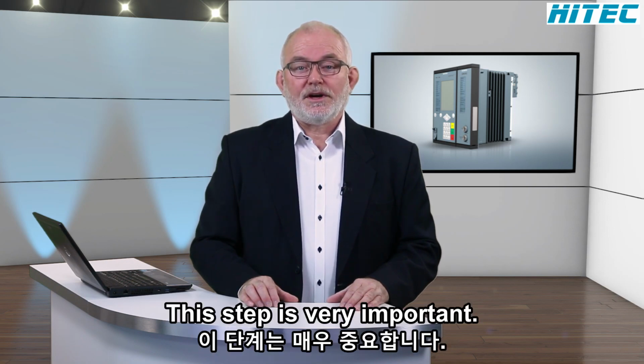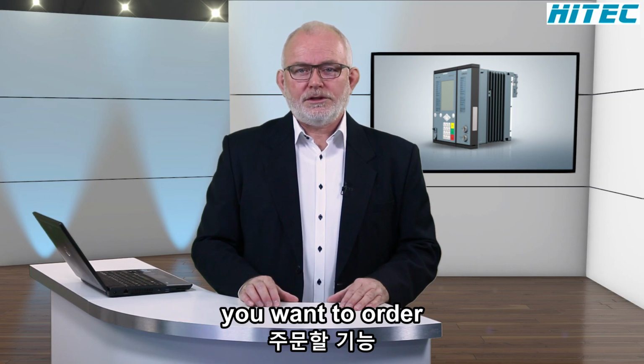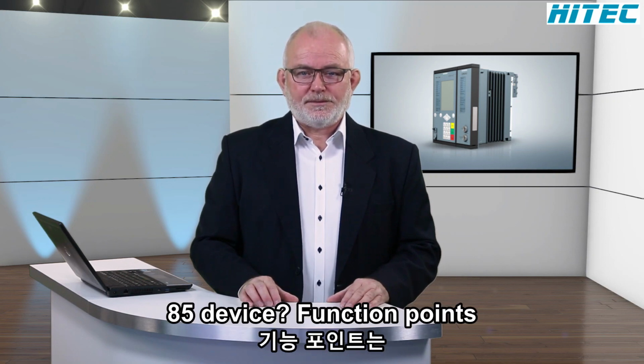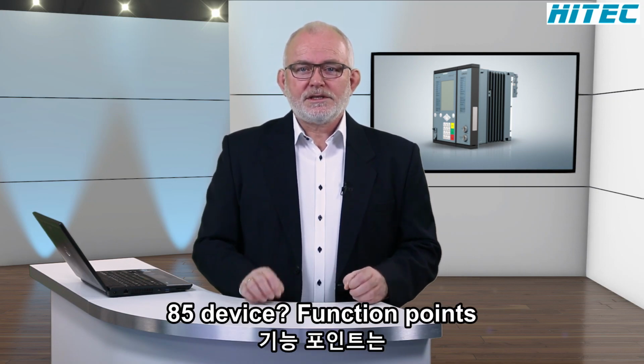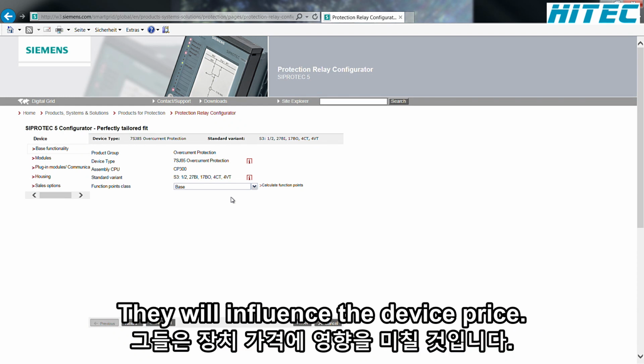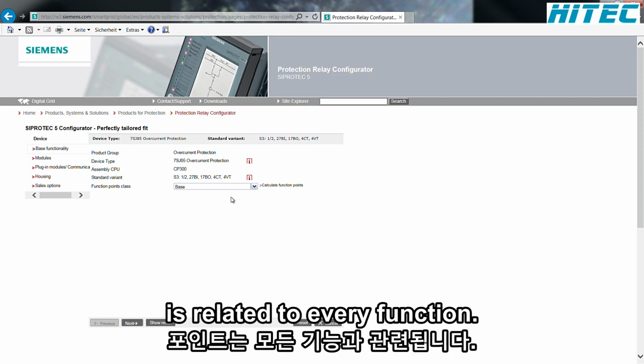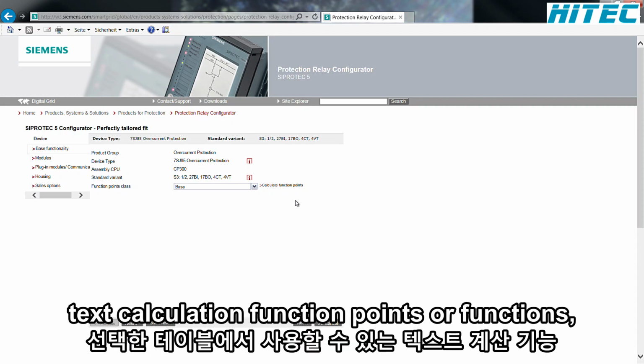This step is very important. You determine how many function points you want to order for your SIPROTEC5 device. Function points are selected in accordance to your needs. They will influence the device price. A defined number of function points is related to every function. We click on the text Calculation Function Points.